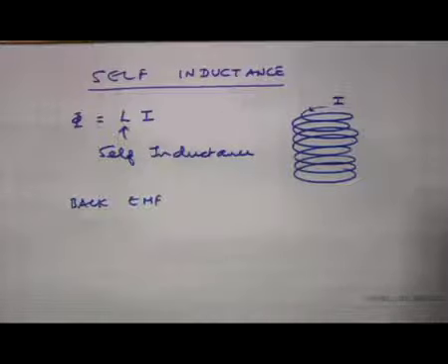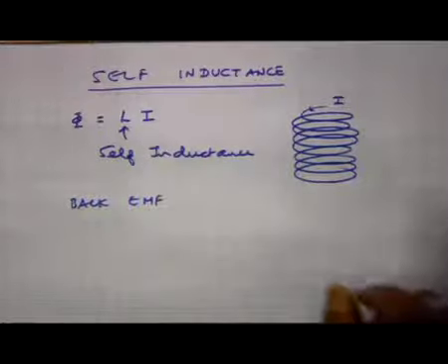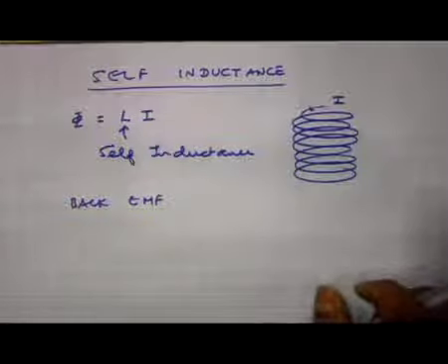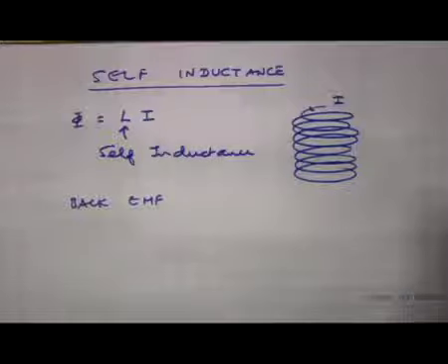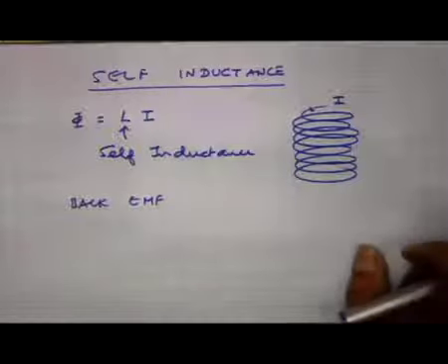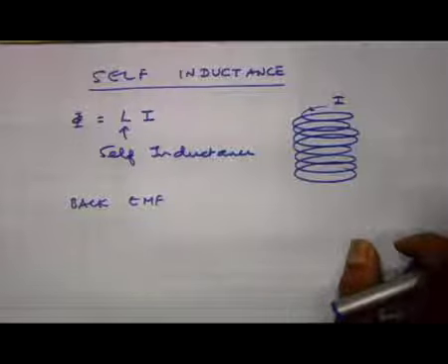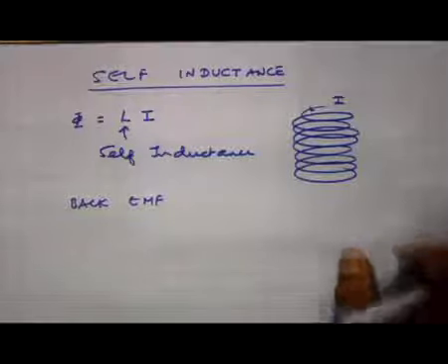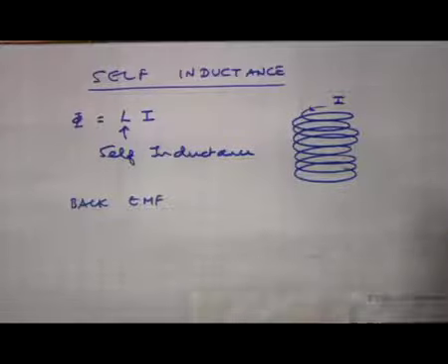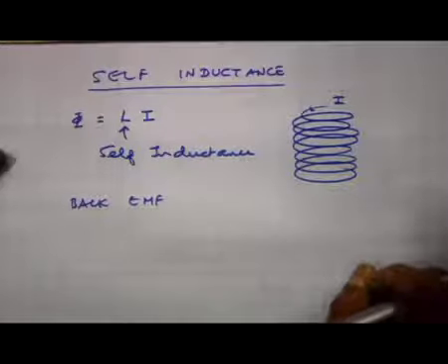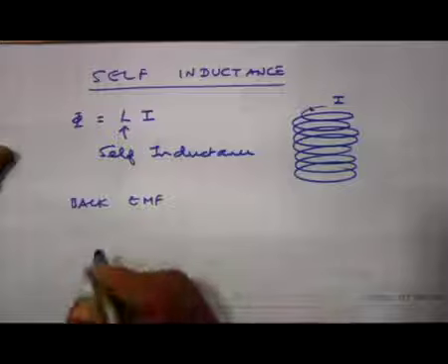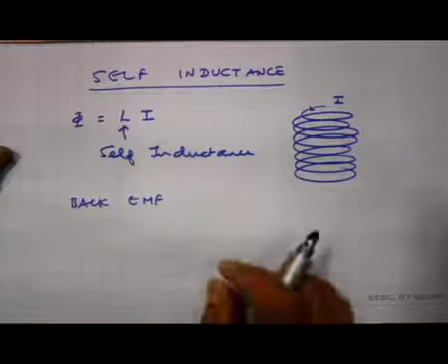So, if you try to change the current in the solenoid, then the changing current induces the changing magnetic flux. A changing magnetic flux induces an EMF, and according to Lenz's law, that induced EMF or current is so as to oppose the change in the current. So, when you try to increase the current, there is an opposing force which is forcing you to slow down. So, this is called the back EMF, and we had seen some examples in the last class.